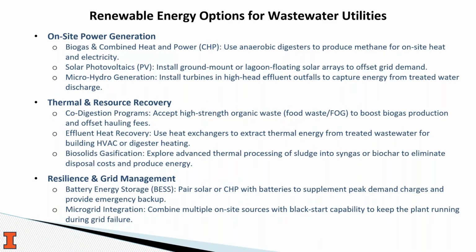I know there are case studies of several facilities that have FOG accepting programs, where a lot of FOG producers can haul that waste to the wastewater utility, and the utility can then add that during co-digestion to improve biogas production. And some utilities are also beginning to explore biosolids gasification, which converts sludge into syngas or biochar, which reduces disposal volumes while producing beneficial byproducts that can be reused.